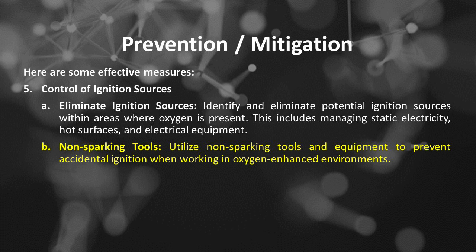Number B, of control of ignition sources is non-sparking tools. Utilize non-sparking tools and equipment to prevent accidental ignition when working in oxygen-enhanced environments.